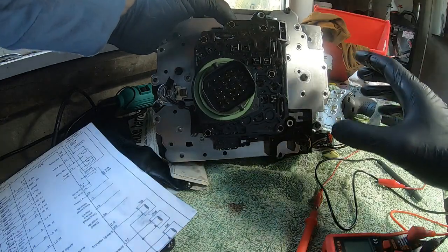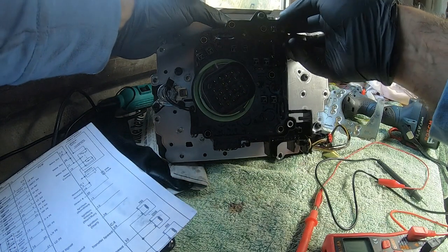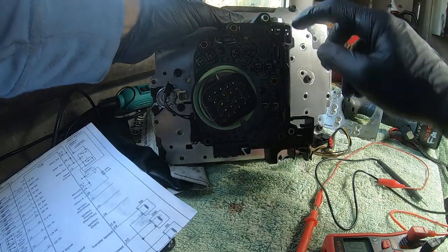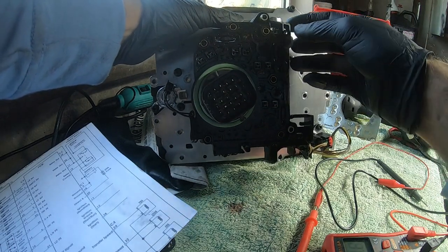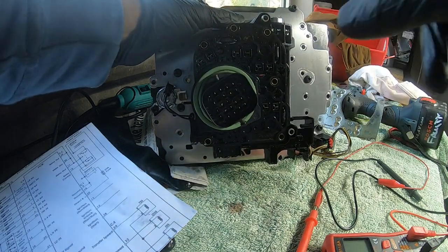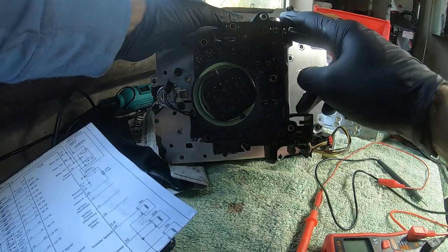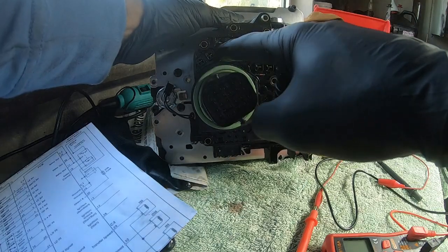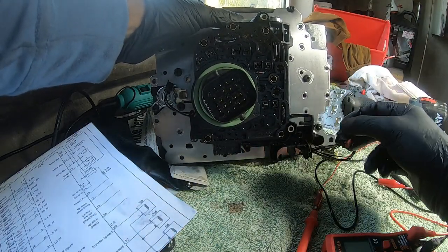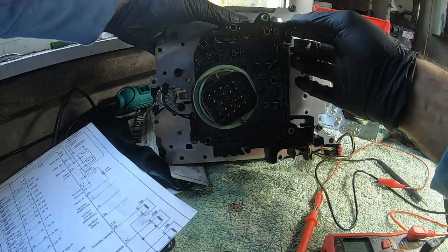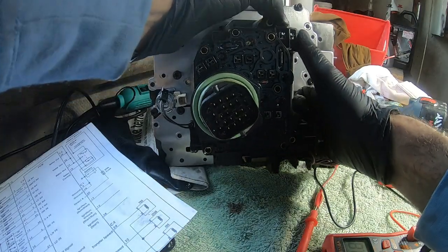So now it is the second stage where you have to remove this thing. The bolts are already removed. All you need to do is, because you can see here, the pins of this particular solenoid went into this black solenoid assembly housing. Same goes for this. There are 2 pins over here and here, and they are holding it down. So you need to carefully pry it out just to make sure that all those wires are disconnected. Slowly pry it out cautiously. It's not going to take much time.